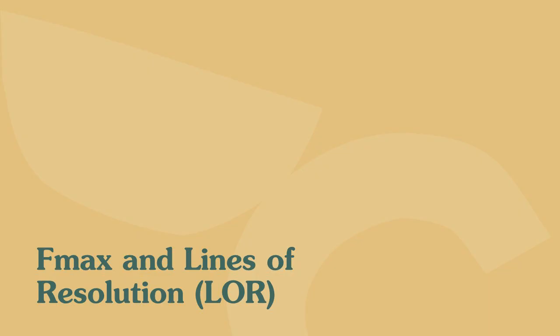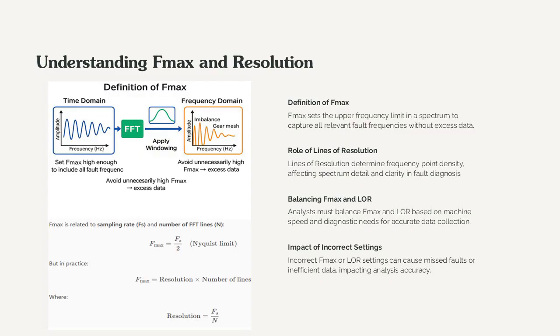Understanding Fmax and resolution. Fmax, or maximum frequency, defines the upper limit of the frequency range displayed in a spectrum. Selecting an appropriate Fmax ensures that all relevant fault frequencies are captured without unnecessary data overload. Here's the definition of Fmax diagram.